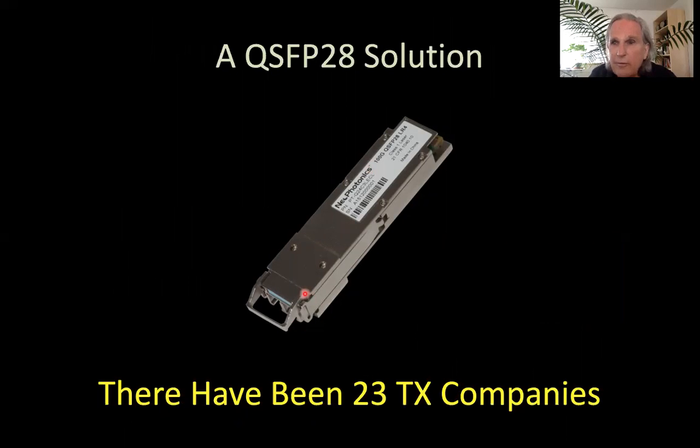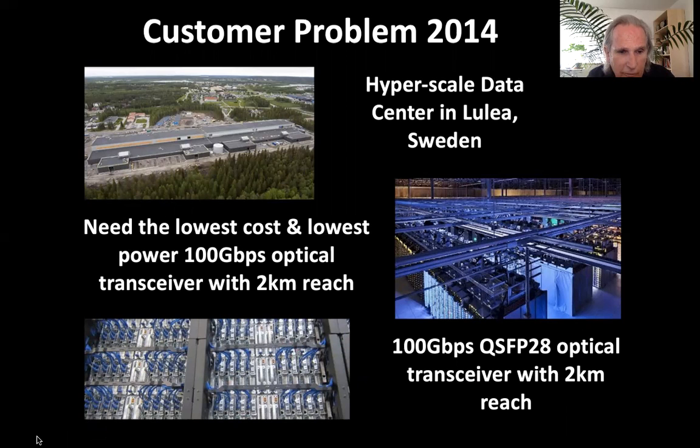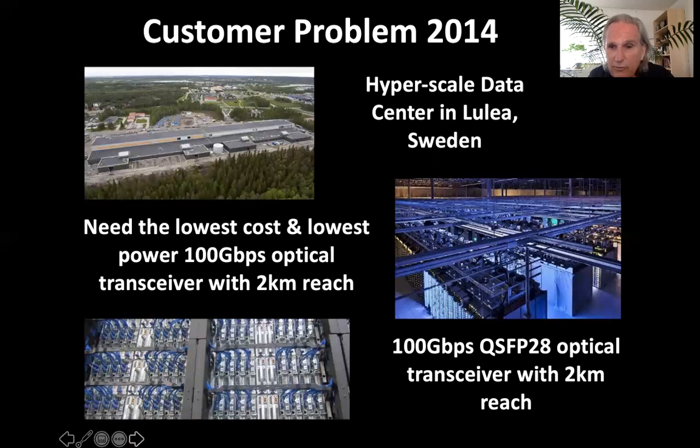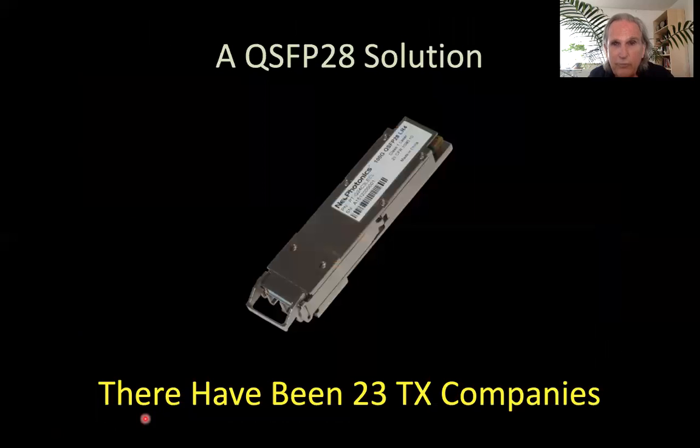And as it turned out, as soon as you needed multiplexing, you needed silicon photonics, because it was the only way you could make the multiplexers small enough that you could actually multiplex signals onto the fiber. So this was when silicon photonics took off. The other thing is, as I showed back here, every one of these leaves needs one, and every one of these leaves goes to a rack, and there are 100,000 racks. So you need minimally 200,000 of these transceivers per data center.